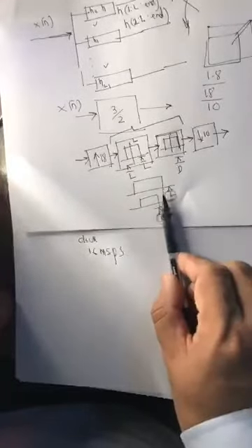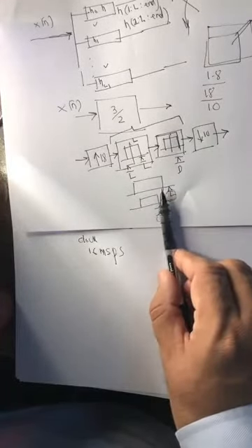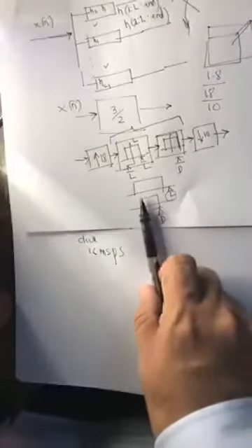Why? Because in the frequency domain they multiply. If one has pi over L bigger than pi over D, then you multiply this with this, and what is left will be this. So it is better that you only pass it through this filter. You pick the filter which is smaller, which has less bandwidth, and you only use that.